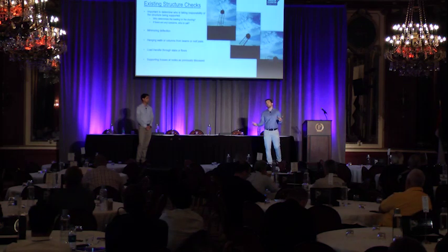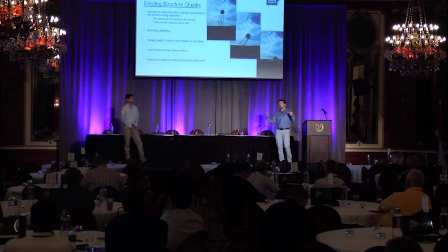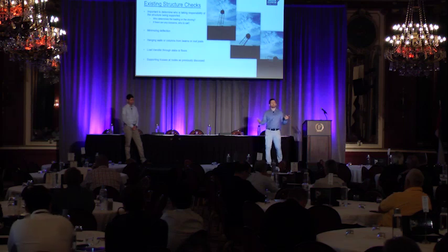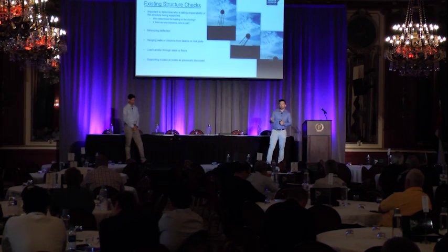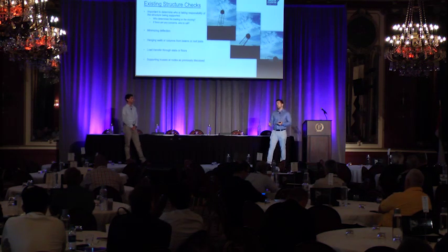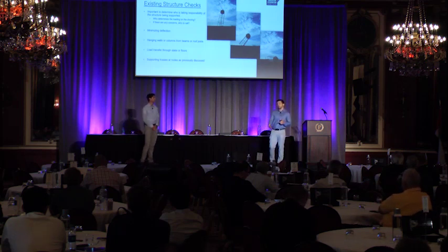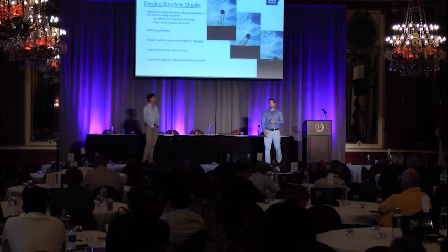Other items are minimizing deflection. A good example of this is if someone's chopping off a column and you install your shoring towers and the system shifts 1/4 of an inch. If there was a prefabricated column that was cut to fit, they have to figure out how they're going to lift that system up a 1/4 inch before they can put that column back in. So it's very important to talk to your client and see if there are any deflection limitations or requirements for the project up front, so they're not trying to figure it out after the fact.